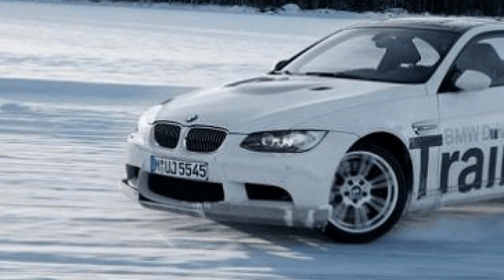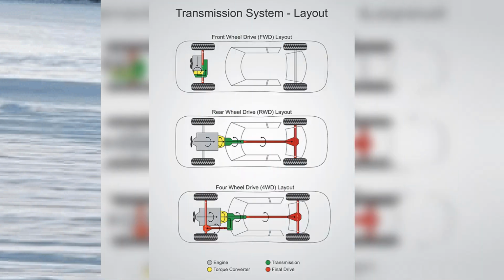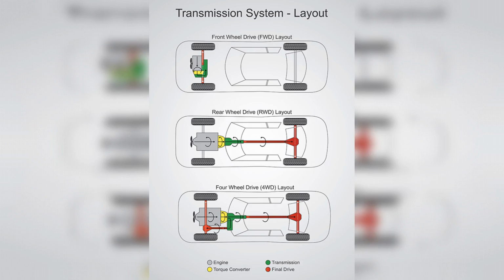Distinctive design features. Continuing to talk about the device, let's compare the transmission design of a rear-wheel drive car with cars that have all-wheel drive and front-wheel drive. Of course, the engine, gearbox and clutch are elements present in all types of construction. The transmission of a front-wheel drive vehicle is designed to transmit torque through the drive axles, which are connected to the gearbox and wheel hub through ball joints, equal angle joints.